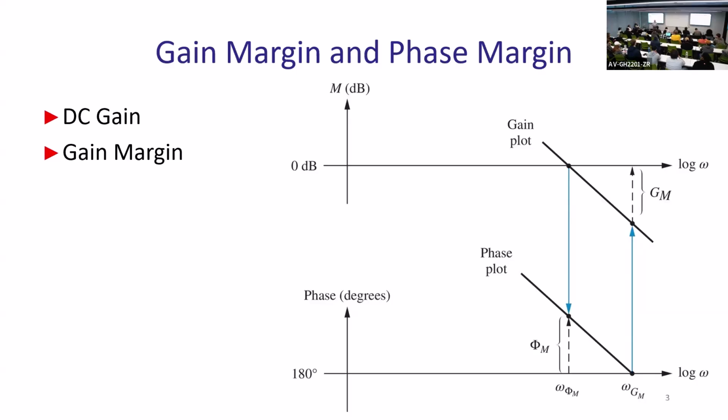And sometimes it might even be positive here, which is worst case, which means the system will be unstable. So you don't have any gain margin really. There's negative gain margin, if you wish. MATLAB will tell you negative gain margin, but it's not really gain margin. You don't have any. So you're taking worst case out of all of the crossings of 180, plus minus.